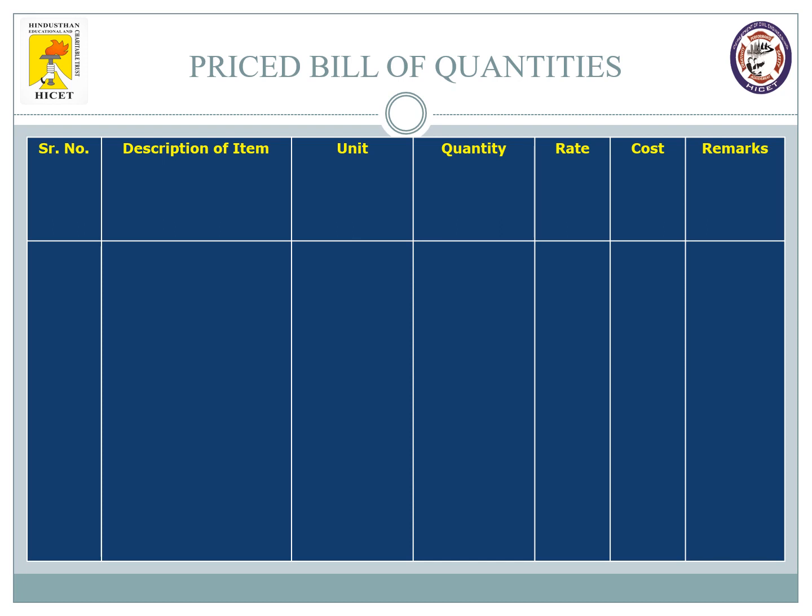Here it is the priced bill of quantities, where we have serial numbers and the description of the item of work. Here we have earthwork, and what is the unit? The rate is already calculated, like one unit is equal to this much amount of money, or two units, three units. The money is written here. That is your rate, and this is the quantity. Like I have 3.25 cubic meters of work to be done. What is the rate for a single unit? So what is the cost?